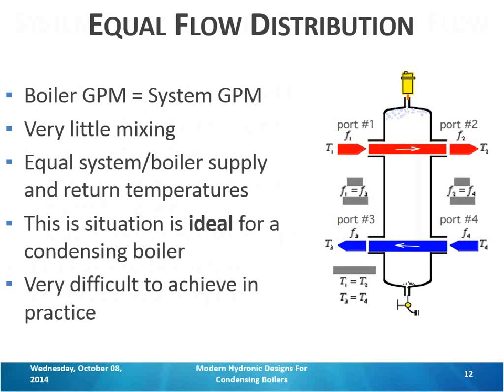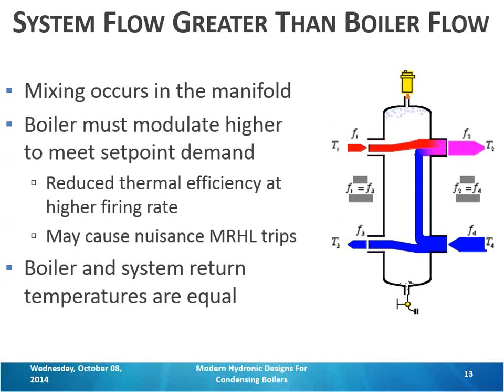In condensing boiler plants, the safety lockout's usually set to either 200 or 210. And they have about a 5% error. So around 190, you're risking a high limit trip. And a high limit trip, for anyone that's not familiar, is where the facilities guy has to go down to the boiler room and hit a little red button or a reset button on that panel. It's a manual reset lockout. And if that happens over and over again, that facilities person's either going to do one of two things. Make a phone call and won't be too happy, or mess with the safeties and they're no longer providing the safety functionality they're supposed to. So it's good to try to avoid that manual reset high limit trip.